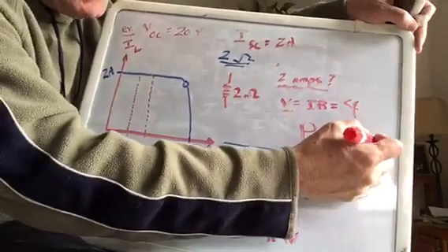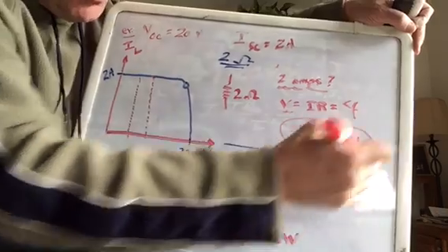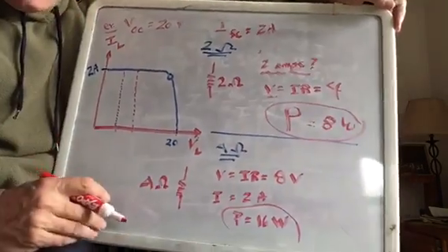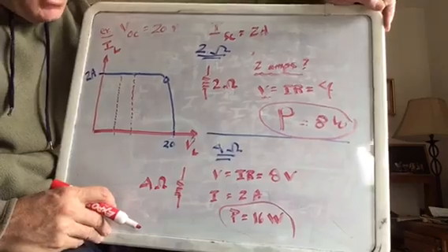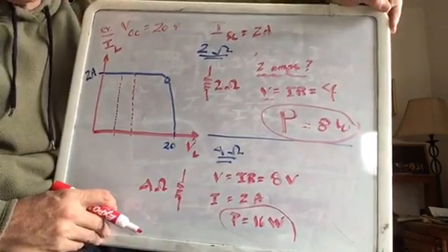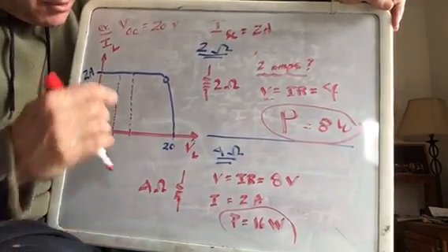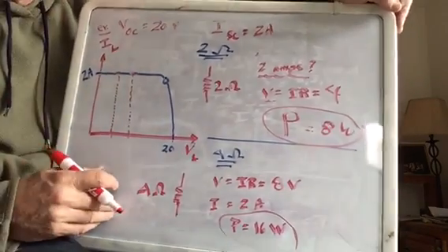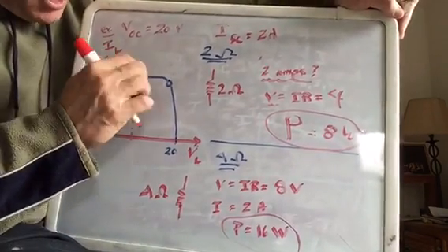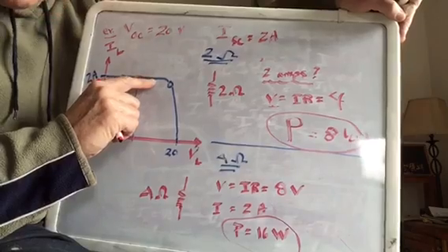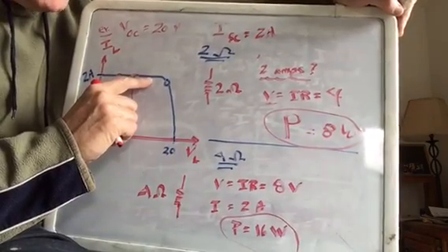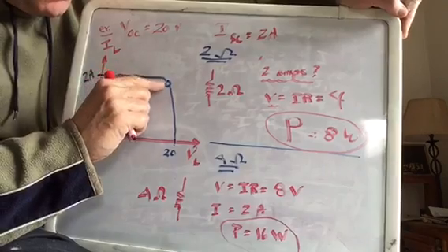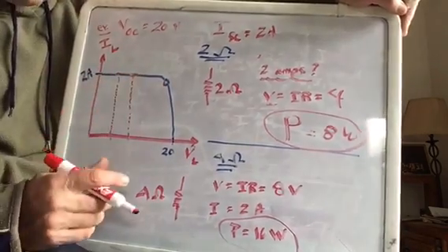And that's the key thing that I want you guys to work on in homework some more, or just thinking about it or looking at the reading. You can see that the power you get out of a PV cell depends on the resistance you hook up. And so over here, we're getting more power than we did at that first point. And as you keep going to the right, you keep getting more voltage and more voltage. That's more joules of energy per coulomb. And right around here, when the current first starts to drop off, that power maximizes.